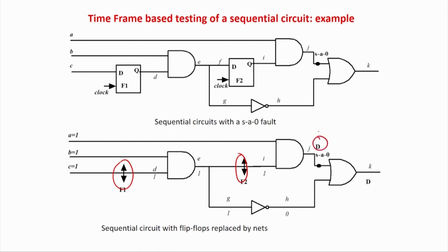Then I have to propagate the value at the output, so I am propagating it. So sensitization is done, propagation is done. Now if D is the OR gate, I am justifying. So D is the OR gate, so I will have a 0 over here, this one, NOT gate 1. Of course, this is an AND gate, so I require both 1 here. So I will require 1 over here. So anyway, this is a 1, the 1 required. Fortunately, there is no conflict.